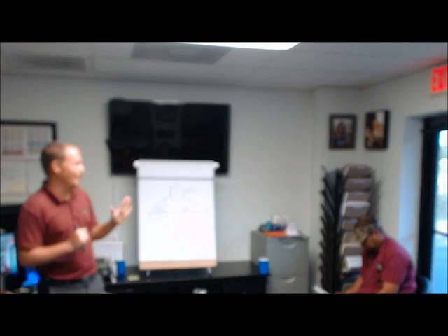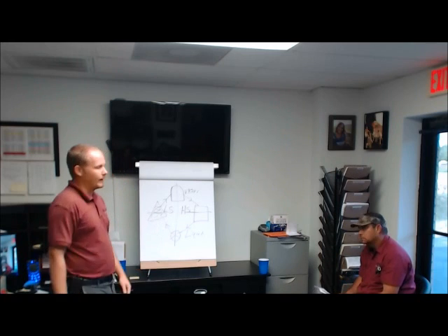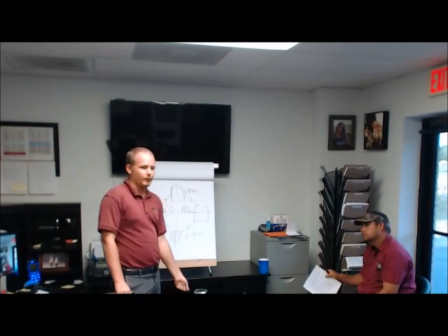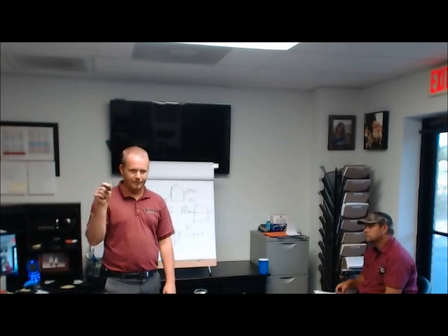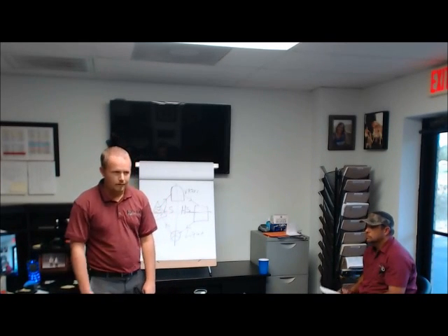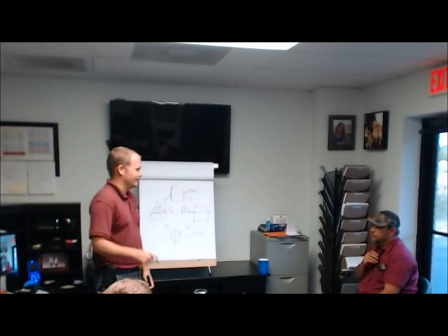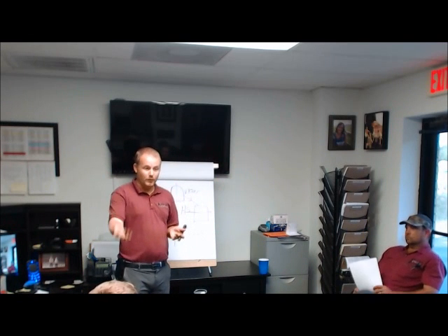Now, let's say you've got a TXV system, you walk up to it and you're running 40 suction on the system, and you hook up your high side and you're reading 150, and the suction line when you come out is warm. What is that going to tell you? Experienced guys here, fill this out. Low on charge. Because I didn't even have to really check the actual superheat on the suction line.